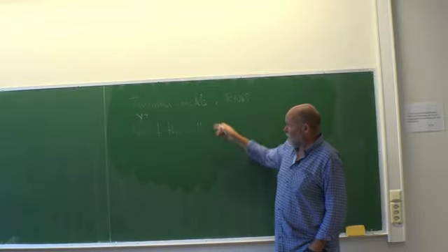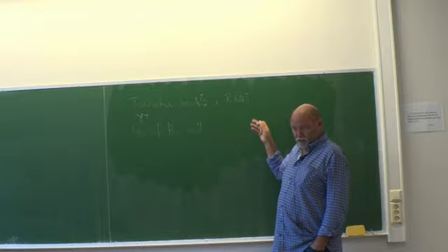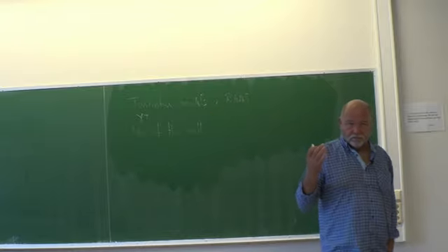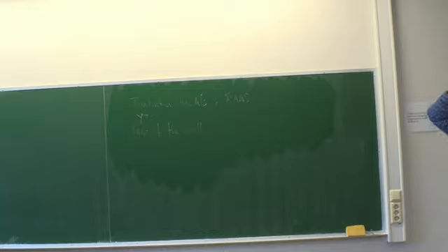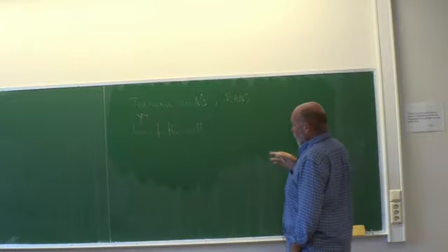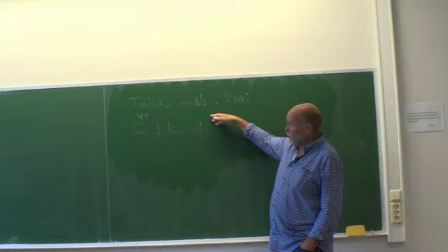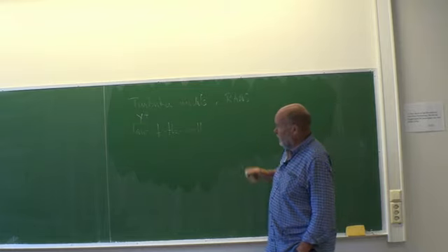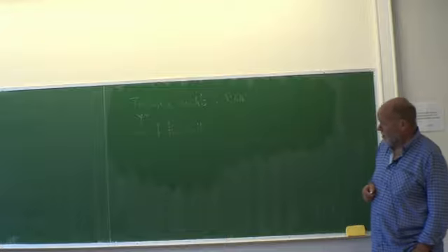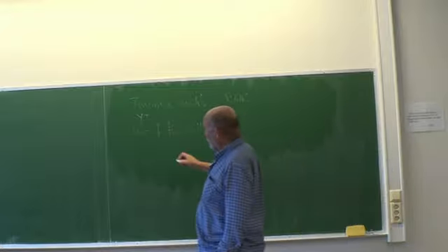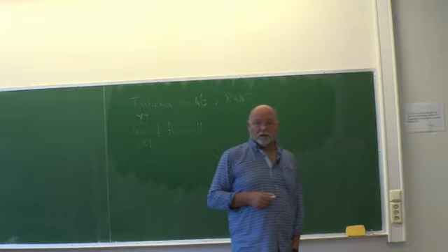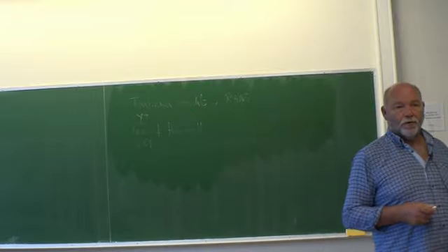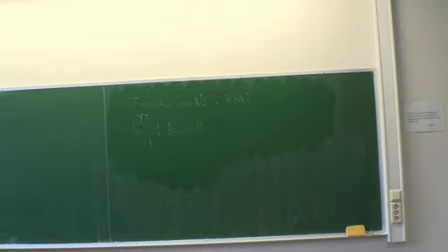I mean, they are connected, sort of decides should you use a model as a function towards the wall, or can you use natural boundary conditions for your turbulent quantities? Very, very essential. And now you have learned about GCI. Also something that should be in your report.